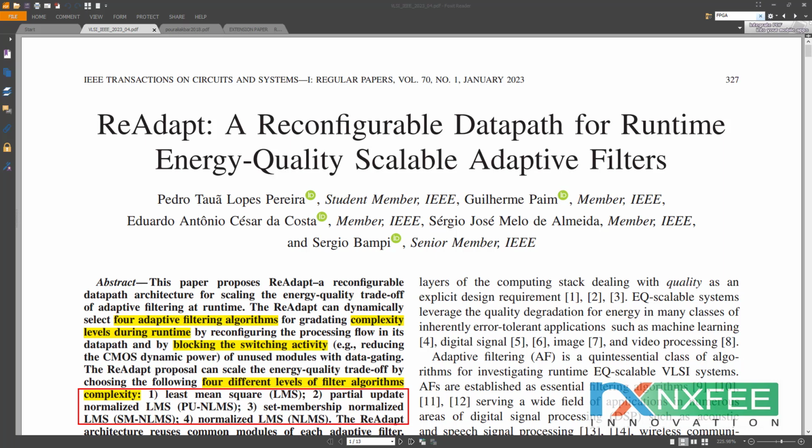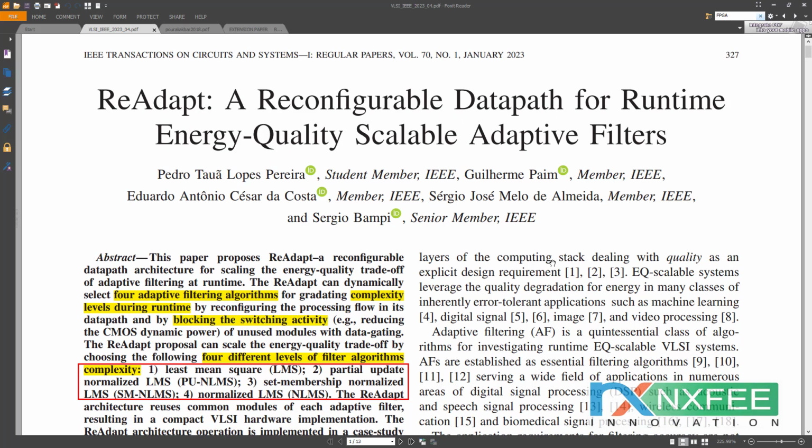So here, the improvement of the project we have developed is to design 4 different adaptive filtering algorithms using 2 different multipliers and prove the performance of area, delay and power. For the existing architecture we have used a traditional binary multiplier design, and for the proposed architecture we have used a reversible Wallace tree multiplier using Toffoli, Feynman and Peres gate architecture. Additionally, exact restoring dividers were integrated in the update control block of the LMS adaptive filter for a higher performance level. So now we can verify the base paper.